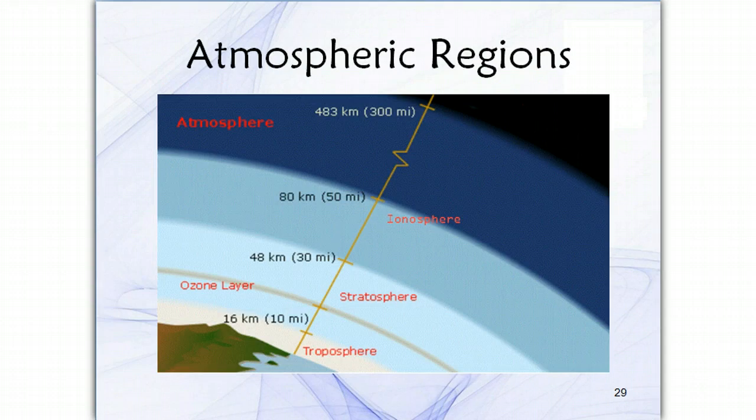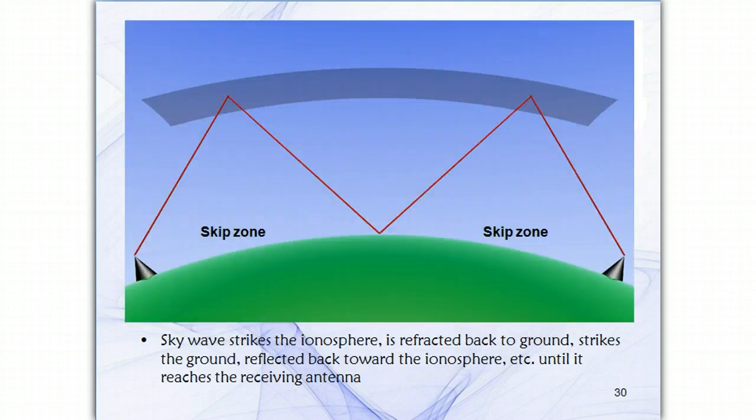Located in the thermosphere, it provides a reasonably predictable means of communicating over long distances using HF signals. The ionospheric modes, such as the skywave. Skywaves are waves that leave the transmitting antenna in a straight line and are returned to the Earth at a considerable distance by an electrically charged layer known as the ionosphere. The ionization levels in the Earth's ionosphere can refract, or bend, the radio waves to return to the surface.